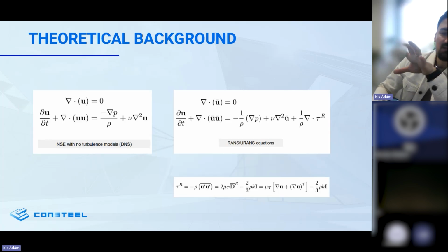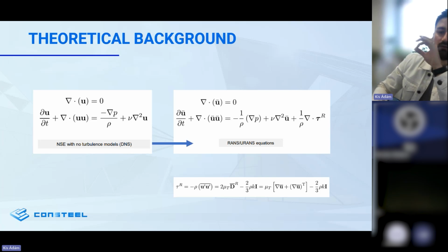But how are these fields, pressure and velocity, related? Well, CFD seeks to solve the continuity and Navier-Stokes equations, in which the turbulent Reynolds stresses are required to be known beforehand. So meaning you need to know a part of the answer before you actually can solve the equations. This is called a closure problem, and the different CFD methods address this in different ways, which balances computational effort against accuracy. Therefore, to efficiently deal with simulations, we are trying to mathematically model several terms.